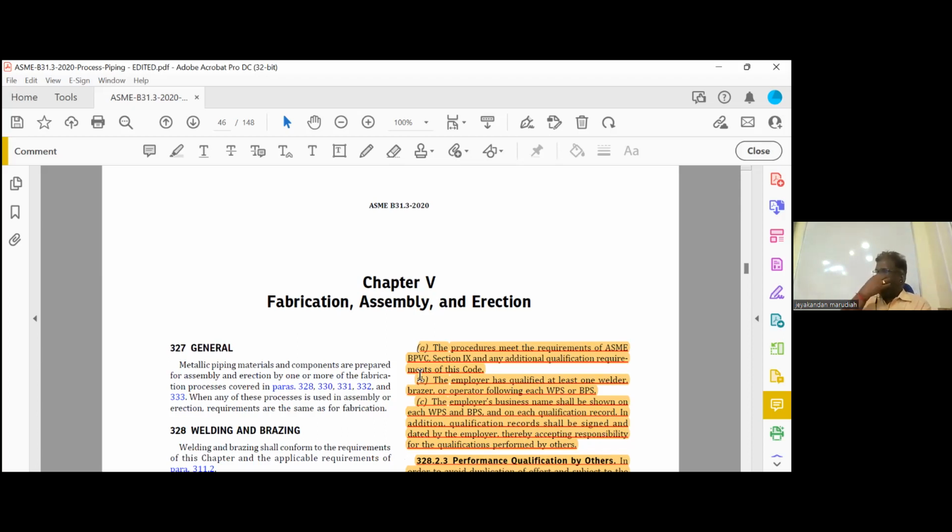Now, you remember pipe can be manufactured in 3 ways. I told you. What are the 3 ways you can manufacture? Seamless pipe, welded pipe, cast pipe. Okay. So for casting, you find the efficiency Ec in appendix A1A. Joint efficiency Ej is in appendix A1B. For seamless, the efficiency is always 1, so no need to search. It is given in Ej.